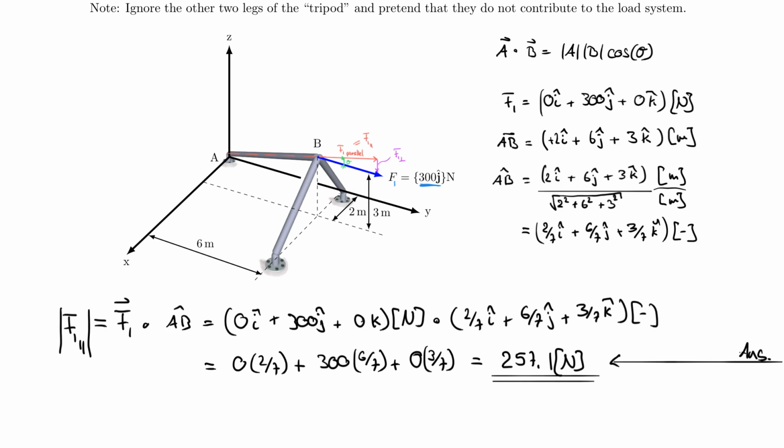Please don't forget this. Now you may ask yourself, but we always have to give magnitude and components. So how do I get my components? How do I know exactly ijk of this force? And the answer is right in front of you here actually, because you already know the direction of this force. The direction of this parallel component is given along this line. And what is the line? The line is given by this unit vector, because the unit vector AB hat describes the direction of this pipe and therefore the extension, which is the parallel component.